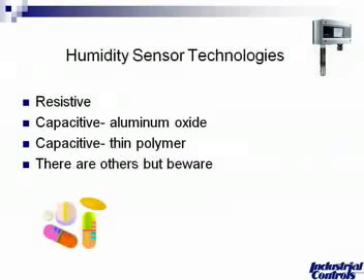There's a whole plethora of different types of humidity sensor technologies out there. I was actually at a customer yesterday. It was an art museum. They had an antique, it looked like an antique. It was a horsehair hygrometer, where as humidity increases, the tension of the horsehair increases, and it was attached to a mechanical arm on the edge of a chart recorder. So those were the early days. Now there are really only a few more common ones, and those are based on polymer and aluminum oxide technologies.